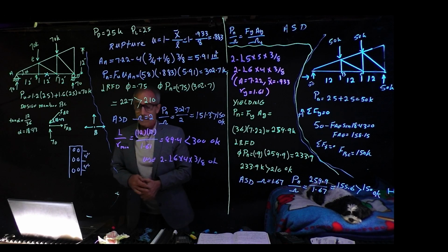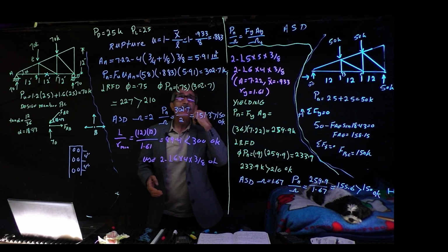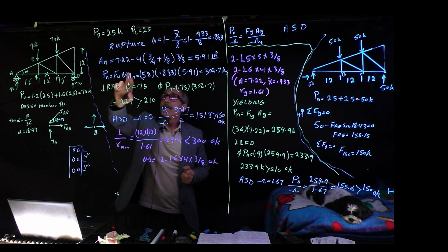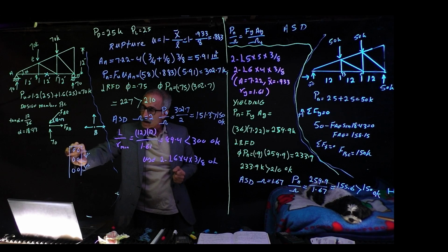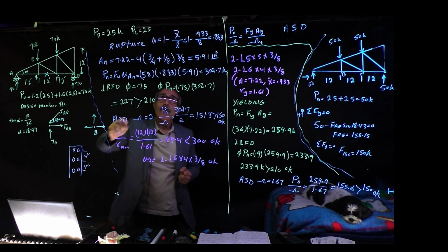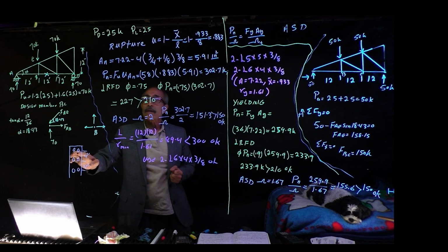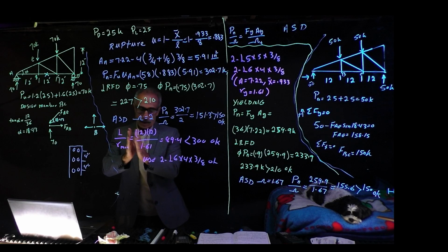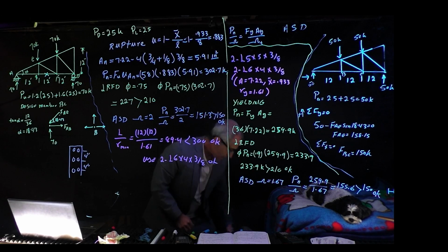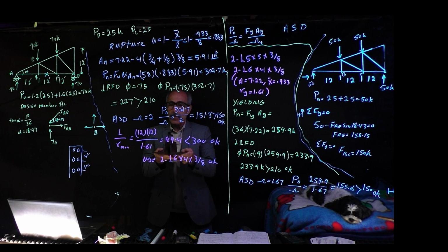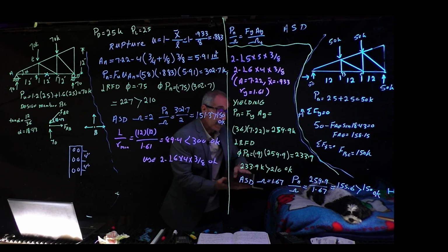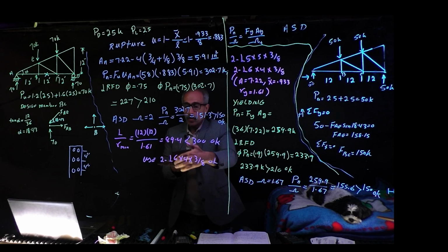That will work. So one thing I want to explain before I finish it up is this 4 holes. You got 1, 2, 3, we got two lines of holes, and then we got two of them 4 apart, so our L is 8. But when we look at the cross-sectional area, because you got 2 angle irons and you got 2 holes in here, you got 2 holes in there, and when you put them together, the entire thing acts as 1 unit. So now I got to deduct 4 holes, because this area is all these 2 combined.